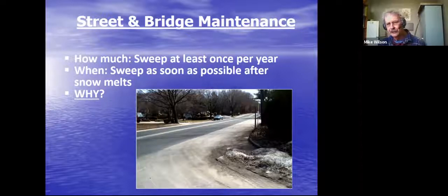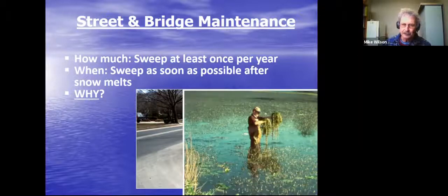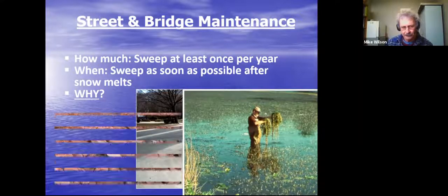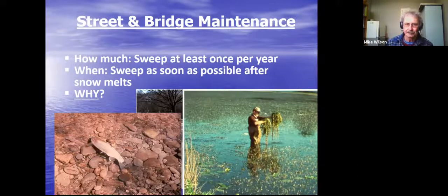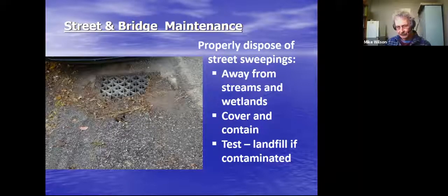So, how often should you be cleaning your streets? At least once a year, and as soon as possible after the snow melts. The reason being is it's laden with a lot of salt. Let's try to clean up that salt and sediment ASAP before our severe summer storms wash it down our catch basins. Because when it does, this is what happens to our waterways. And again, you want to properly dispose of those sweepings, and you want to have it tested if you feel it's contaminated.